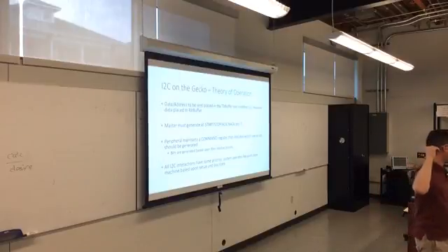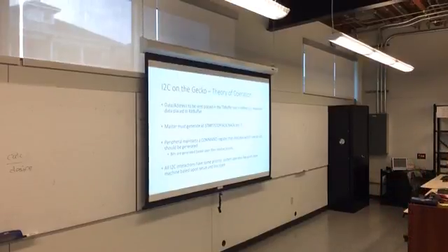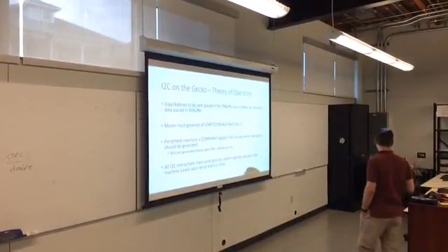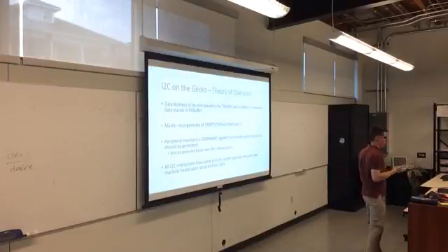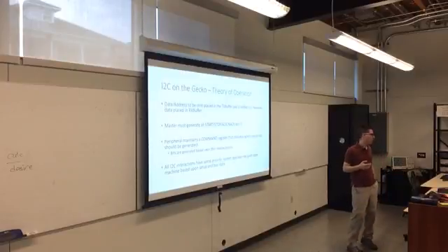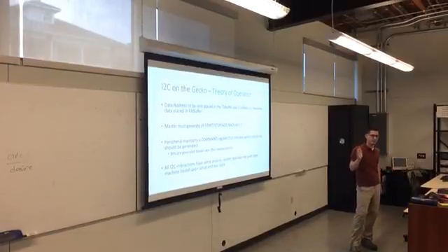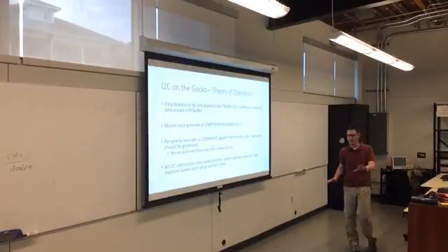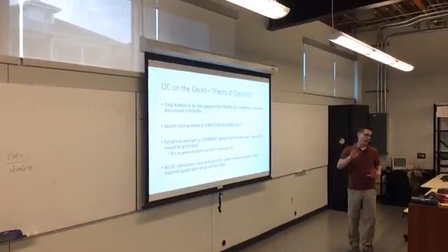Here you have a similar command register that generates NACKs, ACKs, starts, and stops. All of those bits have general sort of interactions and priorities. So if you have an ACK pending but also a stop bit pending, the stop bit is going to have higher priority and just sort of shut the bus down. So you can queue up interactions if you wish, but if you do a higher priority one, it will shut everything down.